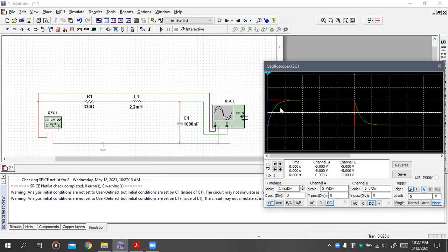Since we could have had the same effect earlier, as in this green color line reaching the red line with a smaller capacitor without bouncing up and down, we can call this an overdamped response. This capacitor is overkill for this situation. We could have gone with a smaller capacitor and had a steeper slope, but yet critically damped.